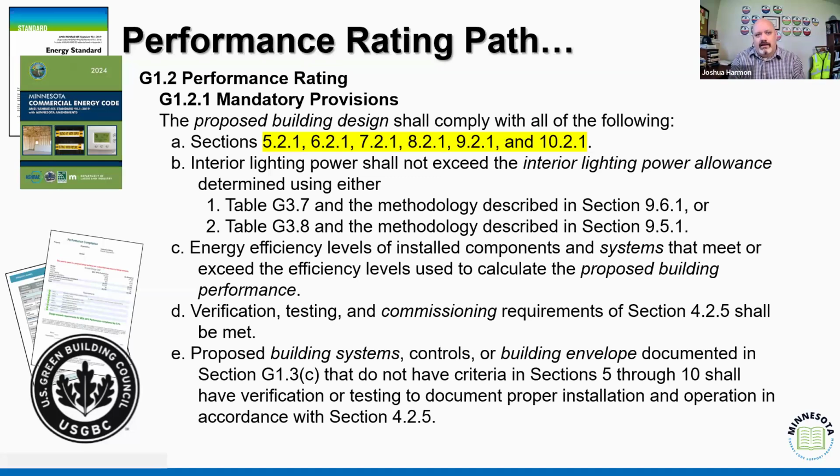If they don't get to provide that final qualitative approval, and let's just be honest, if they go and do an inspection for insulation and the insulation is already covered up by drywall, then they are by protocol required to rate that as a grade 3 installation. There are 3 grades: 1, 2, and 3. 1 is perfect, 2 is a little bit bad, 3 is what was the point of doing it. I'm being super simplistic there; we'll talk about insulation grading later. But if they don't see it, they have to rate it as a 3, which then affects the cost calculation and how the energy modeling works with the system.